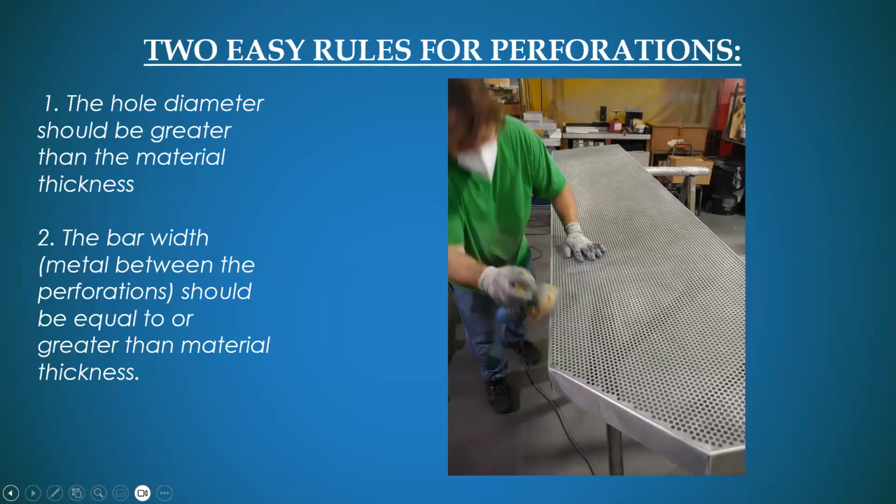Generally, most of these projects you're about to see are using a 1-inch hole when they're round holes, and that becomes pretty nice from street level view. So be very careful of those tiny little holes, and again, metal thickness is critical as well. I don't think we do much of any real exterior perforated panels that are less than 1/8 inch, 0.120.